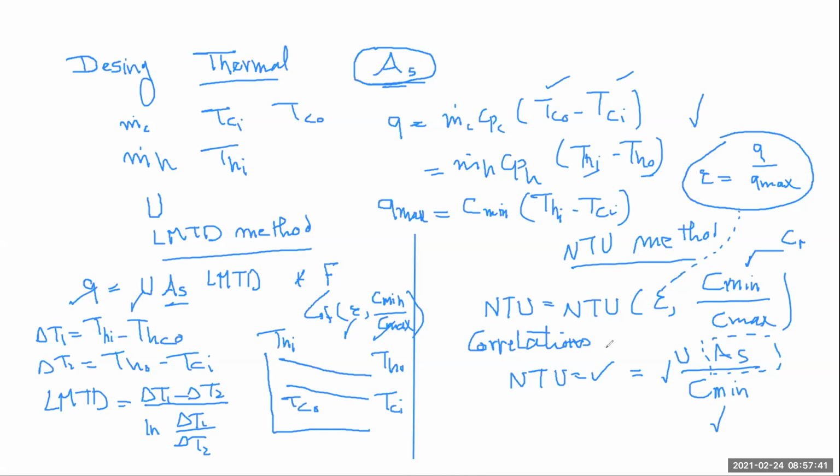So please refer to your chapter at section 317. It might be given an example on rating of heat exchangers. Just go through it. It will be an application to the first part of what we discussed today, which is rating of heat exchangers. Again, rating is performance analysis where you have an existing heat exchanger, you know its surface area, but you need to predict how good it will operate, what is going to be the heat transfer rate, Q, which is sometimes called heat duty of the heat exchanger.